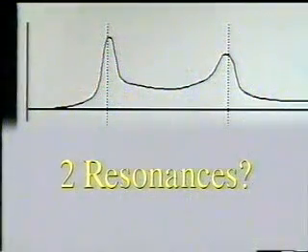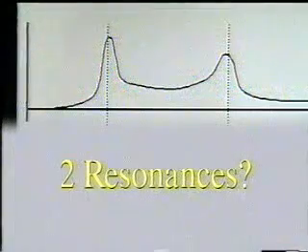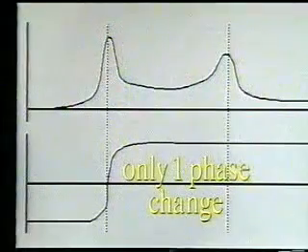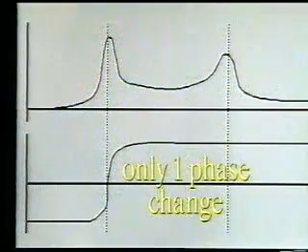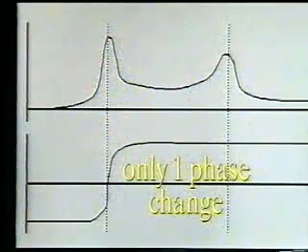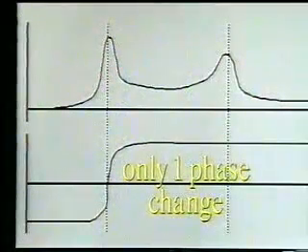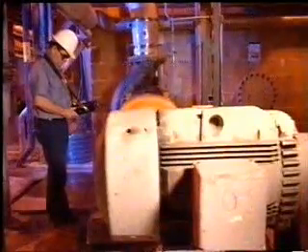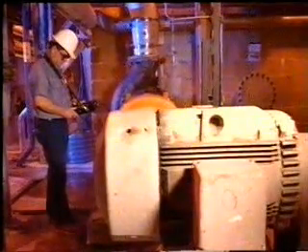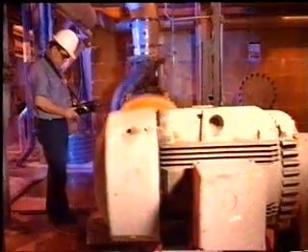This coast down plot has two high areas of vibration that at first seem to indicate there are two resonances. However, when viewing the phase plot, the phase changed at one of the high amplitudes, but not the other. Without a phase change, the machine did not go through a resonance. The high vibration at this frequency is from some other source. In areas where multiple machines are running, the high vibration could actually be from another machine.